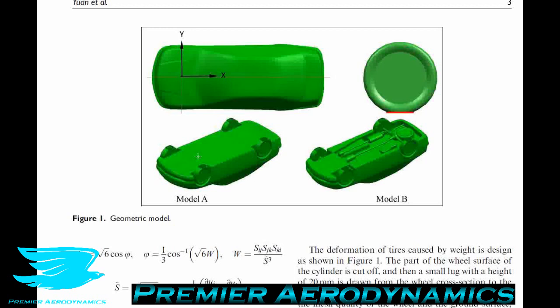And this is becoming more and more common in automotive engineering. If you look at a manufacturer, an OEM, and you get a car and look at the underbody, there's a good chance these days that the underbody will be covered. And there's a very good reason for that. The reason is that this typically reduces the drag of the car, and also allows the diffuser to work better.